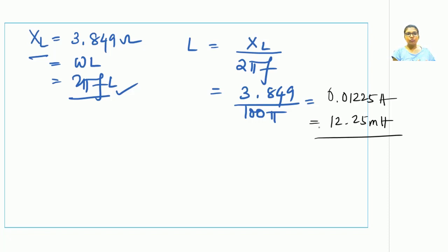Now we have already almost solved this numerical. Now one can think of a different aspect of this numerical. Instead of the lagging angle, if the leading angle is given to us, then it would imply a series RC circuit. And from there we can figure out the value of R and the capacitive reactance. And what would be the load capacitance?